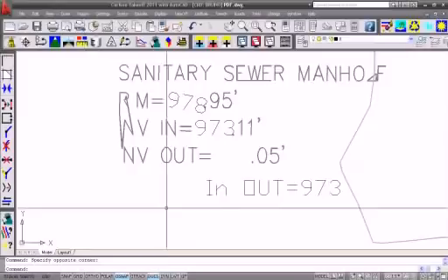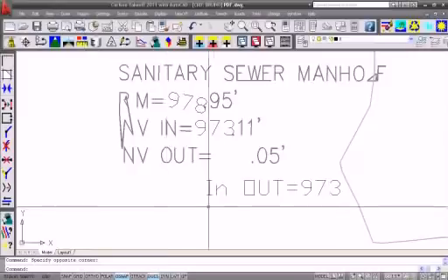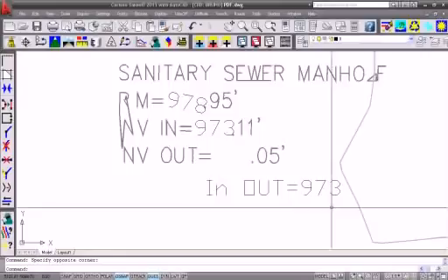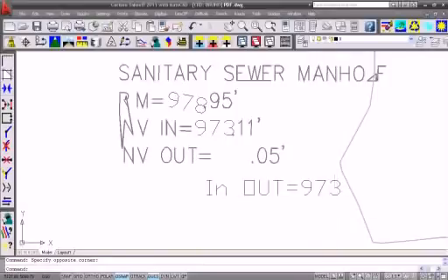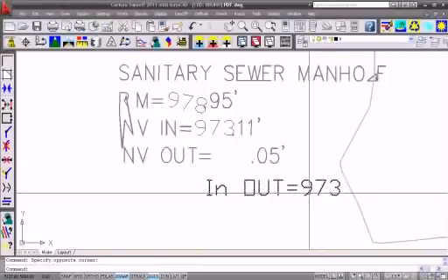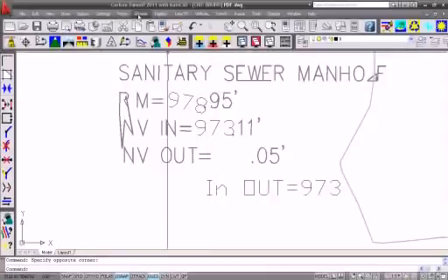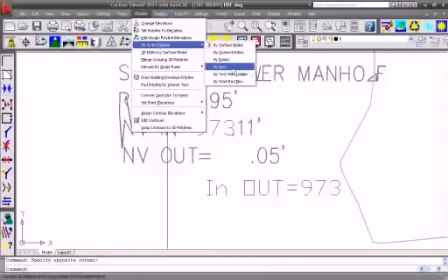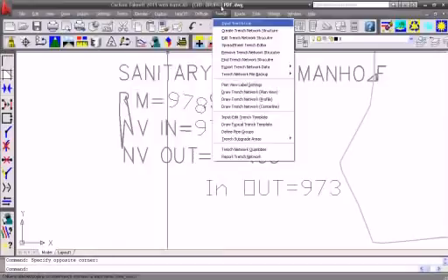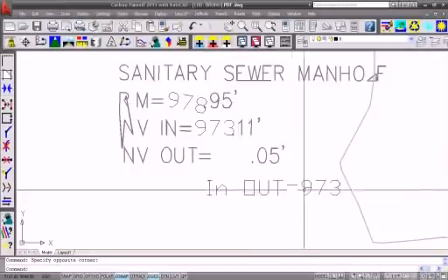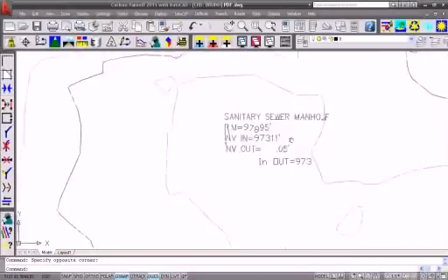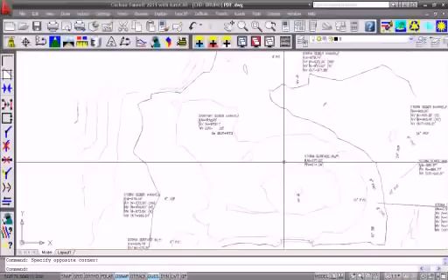So if we had a lot of leader lines for a 3D line or a curve, we could convert all those leader lines into actual text, and then run elevate 2D to 3D by that text. Whereas before, that line work would just be dead to us. So we now have the ability to work off of that line work and convert it in the drawing.